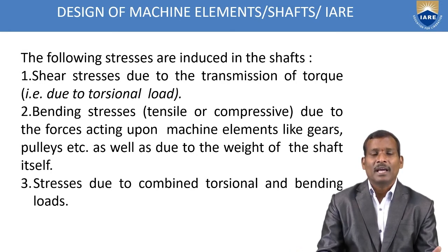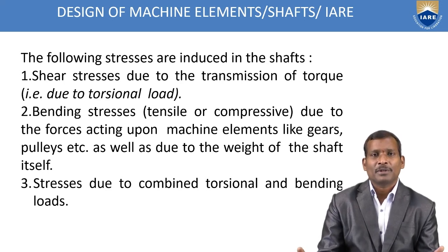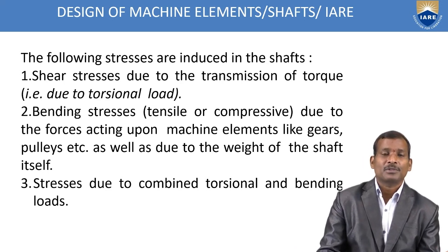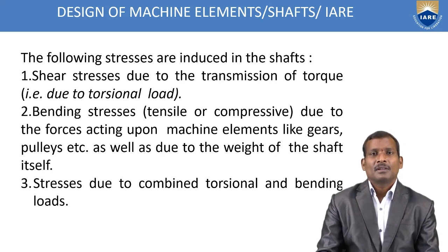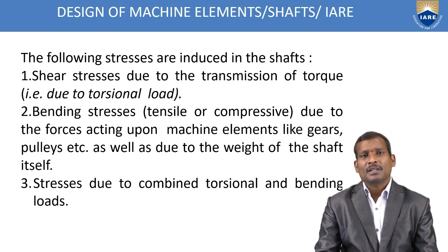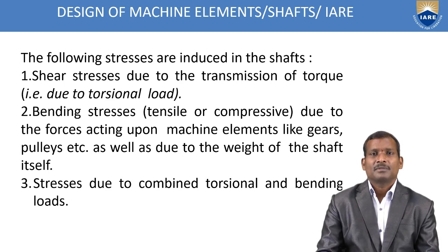So you should learn, before designing a shaft, what are the stresses induced, and what are the standard stresses for a particular material. It depends upon the material also. And you should use some theories of failure. You know, there are 5 theories of failure. Already we have studied them while designing a shaft on the strength basis when it is subjected to bending and torsion loads.